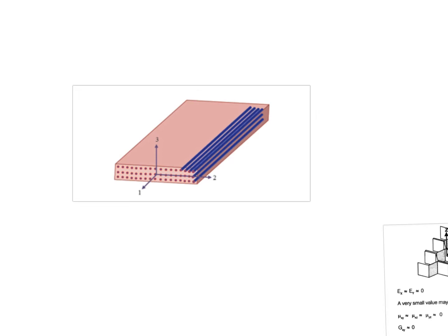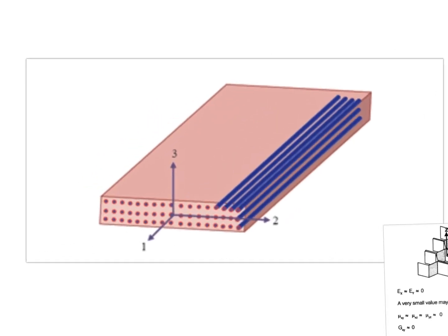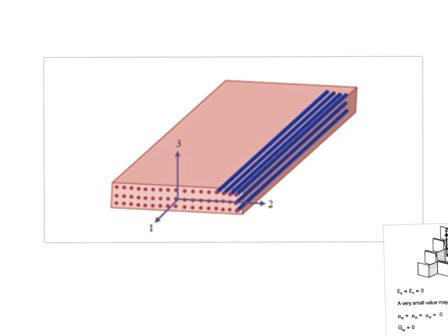Another classic example of an orthotropic material is a unidirectional lamina. Actually, this is a very special case of an orthotropic material, but for the time being, you can think of this as an orthotropic material. You can see the properties will be different in the fiber direction, and the properties will be much better along the fiber direction, and not that good in the direction transverse to the fiber. They may be slightly weak. Actually, you can call this transversely isotropic also, but I'm not getting into that.